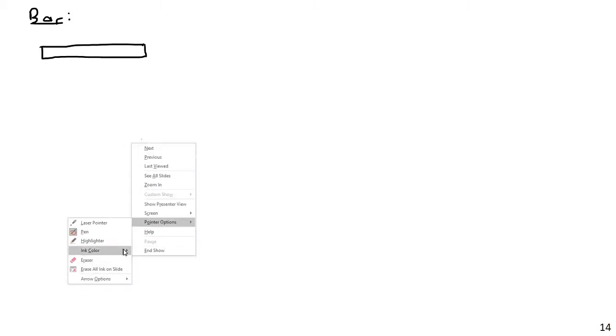Let's say at the end of a beam here, there's going to be two different stresses present. One, there'll be the actual internal tension present at the end of the cross section. That's our T that we refer to usually, our T load, our actual tension in the rebar. And then for any given section of rebar, we'll also have this kind of skin friction. This is the frictional force resulting from the concrete gripping the steel, gripping the rebar. So we have this sort of skin friction effect.